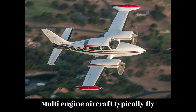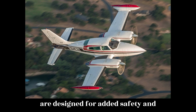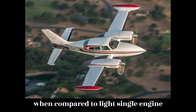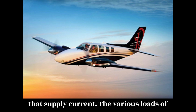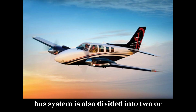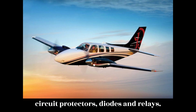Multi-engine aircraft typically fly faster, higher, and farther than single-engine aircraft. Multi-engine aircraft are designed for added safety and redundancy and, therefore, often contain a more complex power distribution system when compared to light single-engine aircraft. With two engines, these aircraft can drive two alternators, or generators, that supply current to the various loads of the aircraft. The electrical distribution bus system is also divided into two or more systems. These bus systems are typically connected through a series of circuit protectors, diodes, and relays.